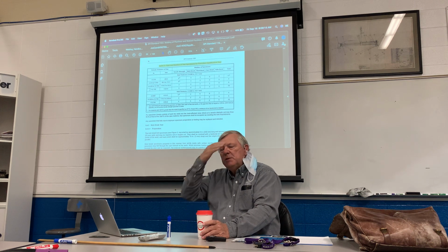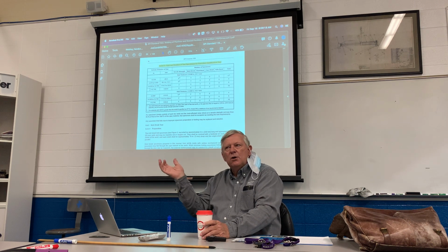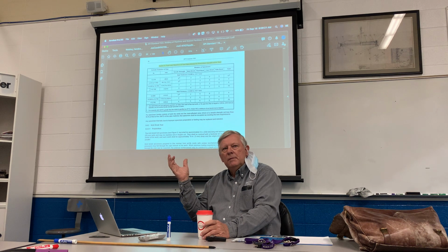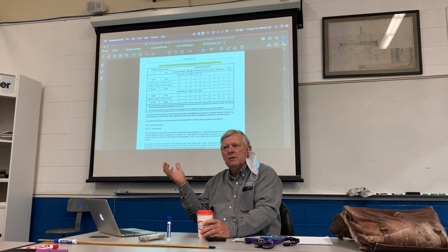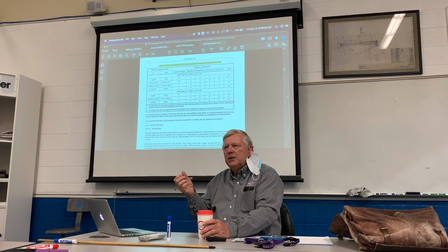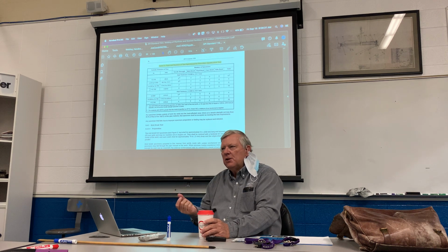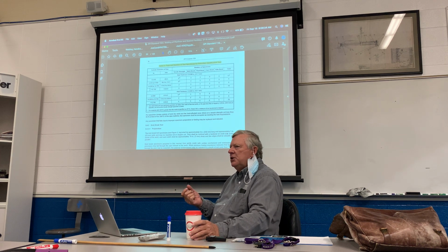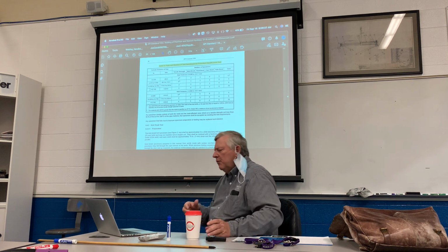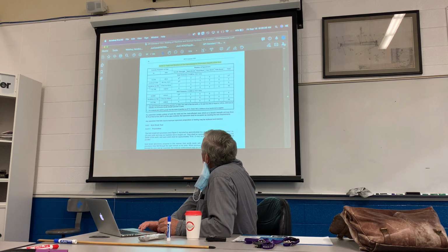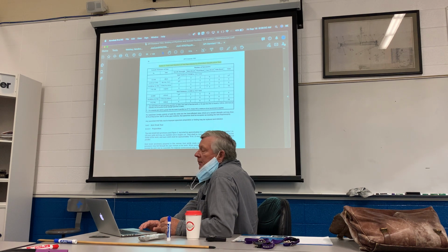It's correct. If you do 12-inch pipe, you're qualified for all pipe sizes, all wall thicknesses, depending on what position you do it in, but everybody does an API test in the 6G, which is the hardest one. And for a welder, 6G is the easier. 5G is the hard one. Because with 6G, you're kind of doing a horizontal. If you've welded enough, you understand it. But for, you find the outside diameter, this is just in millimeters, 4 tensiles, 4 nicks, 4 roots, 4 faces, just like we saw in the diagram. Okay? For a total of 16.